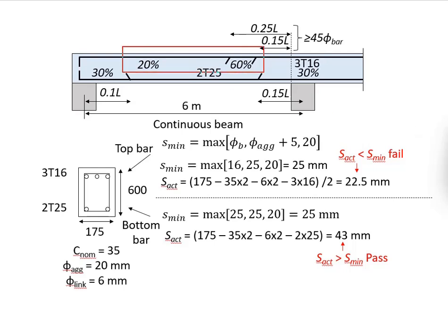And then after the curtailment, the amount of reinforcement bar should theoretically be reduced. Therefore, we're going to check the minimum spacing available within the reinforcement. First, let us deal with the bottom reinforcement bar here.